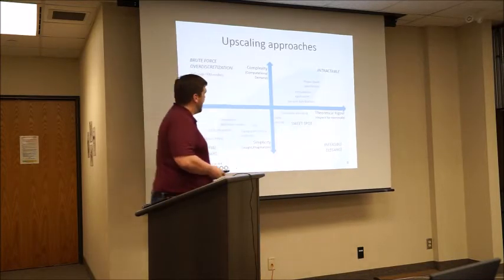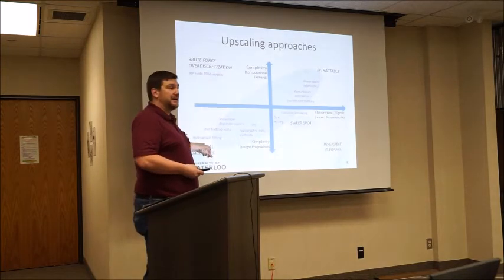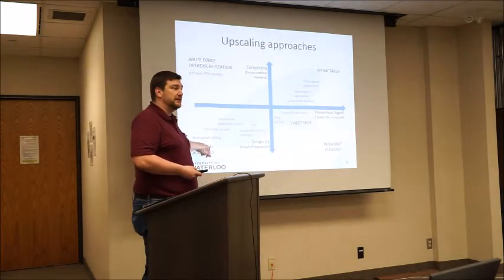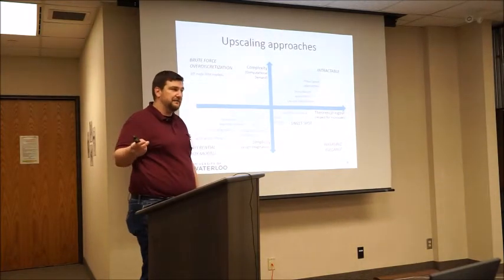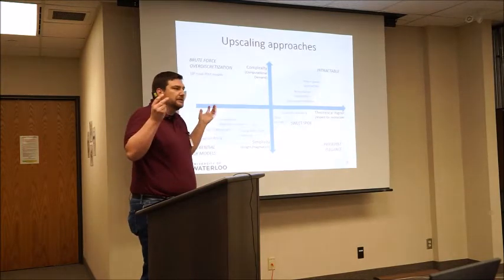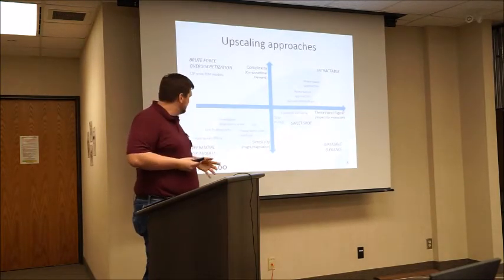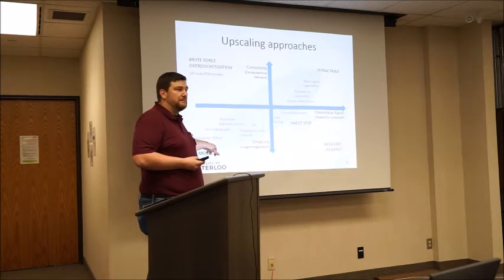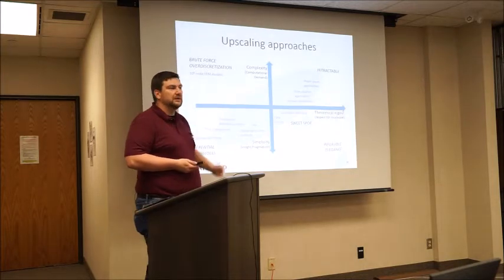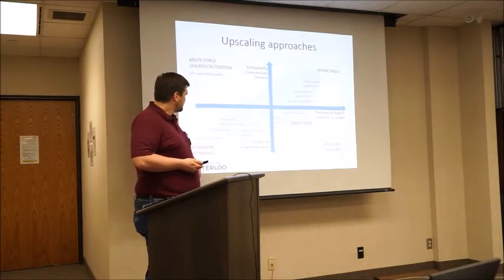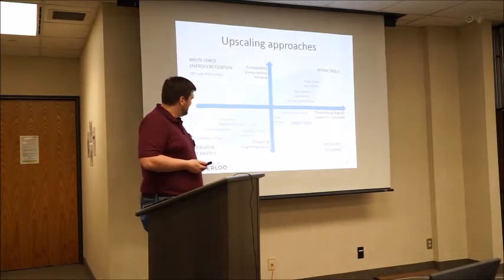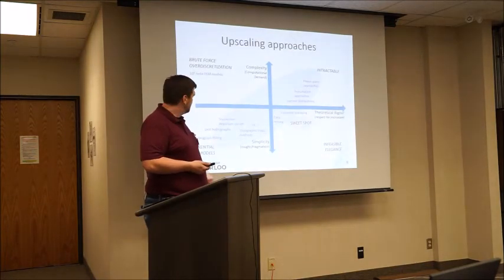And there's a range of tools, from hydrograph fitting. This is a form of upscaling. We're inferring from the hydrograph, using box models that are conceptual descriptions of the landscape, what the bulk behavior of the system is. So this is regression, various regression methods for fitting base flow coefficients, for example.